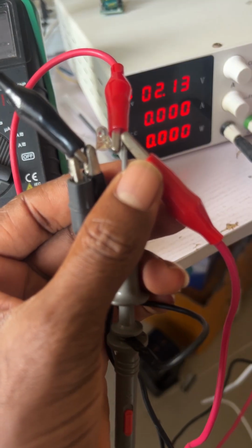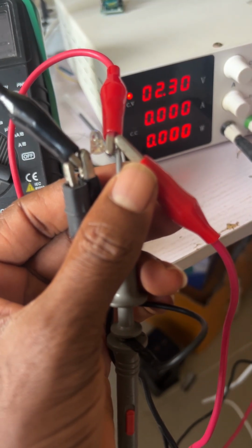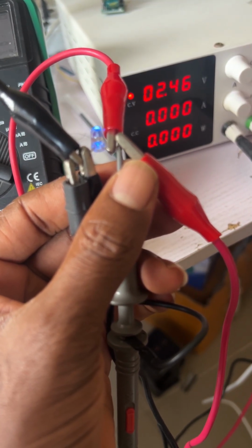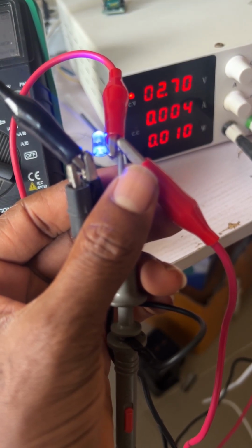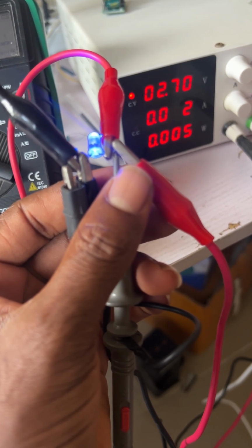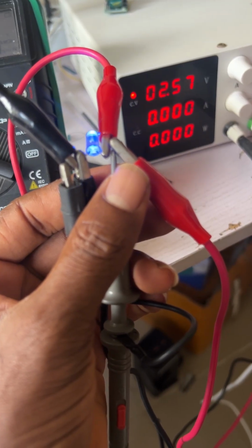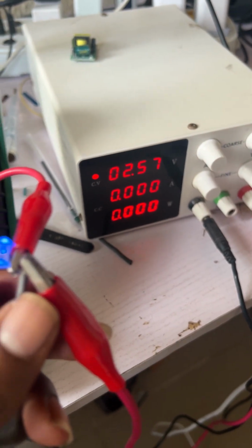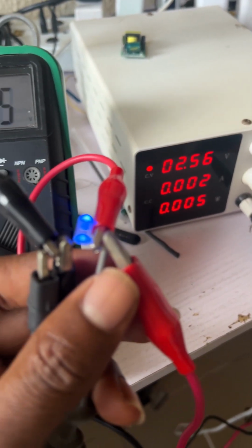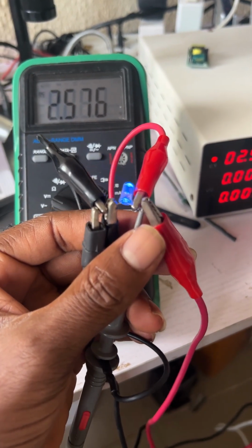It didn't even turn on at 2.1 volts. It turns on at about 2.5 volts. Now, if you look at the meter, it's showing 2.5 volts. Our power supply 2.57, and this is my LED, right? Now let's go to